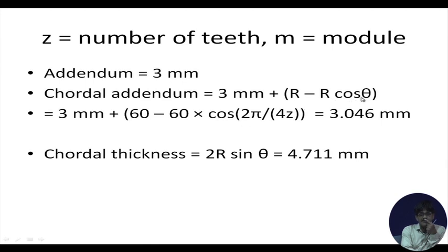Either if theta is not correct, there was some problem with the indexing. If r is not correct, there is some problem with the adoption of either the depth of cut or the outside diameter. As it is made up of r and cos theta, at least one of them must have been at fault. So, with this we come to the end of the 9th lecture.